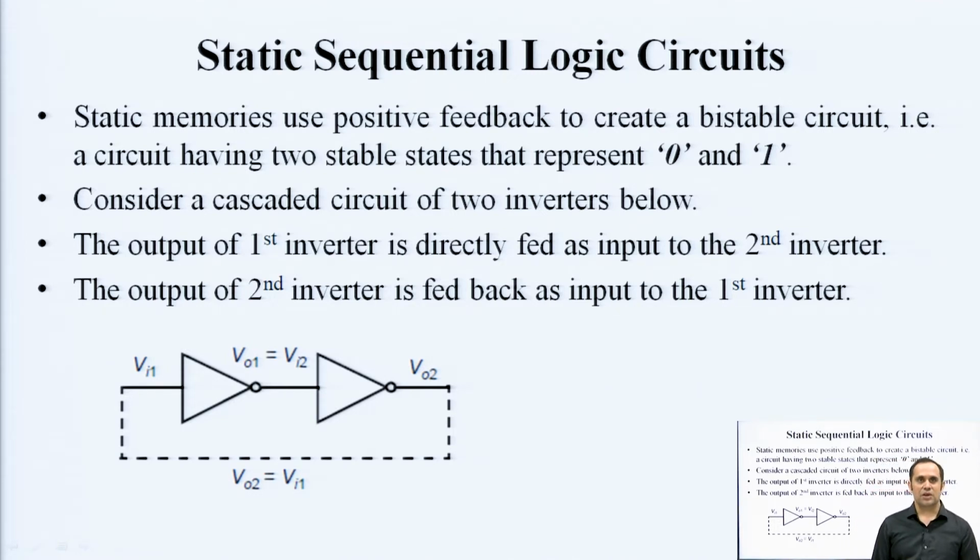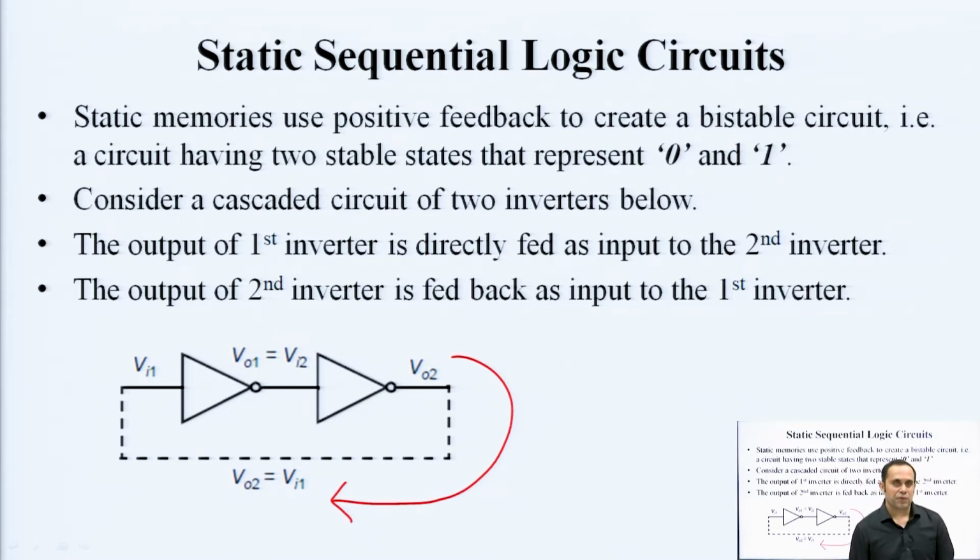A static sequential circuit, a circuit which has a static type of memory, is one which uses simple positive regeneration from the output to the input. Whatever is available at the output is fed back as it is to the input, and it is generally always available as long as the circuit is switched on. So, consider this circuit here,